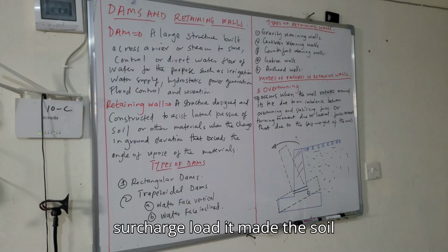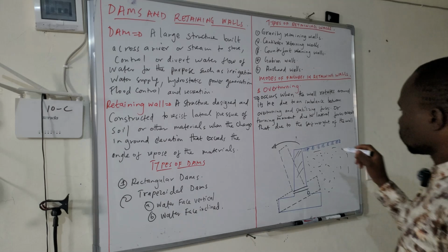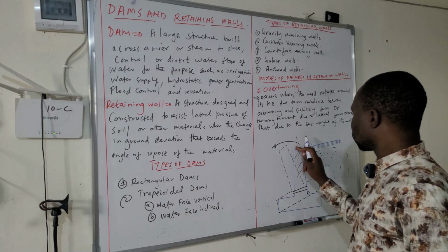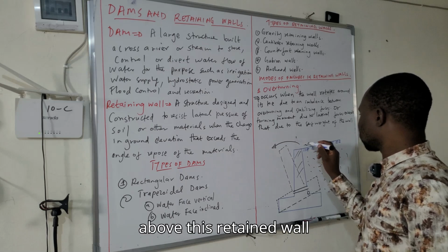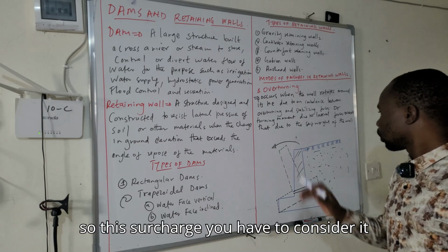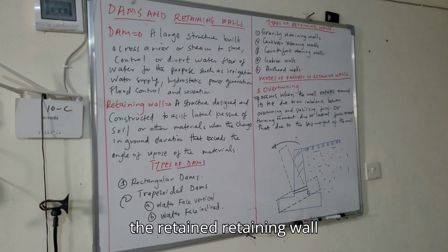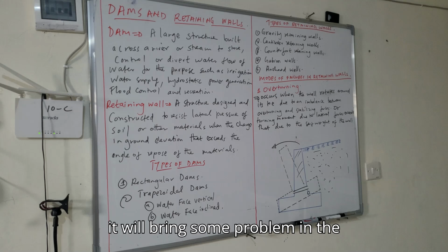The surcharge load may be the soil placed above these retaining walls, yes, soil above this retaining wall. So this surcharge, you have to consider it when designing the retaining wall. If you don't consider it, then it will bring some problems in the future.